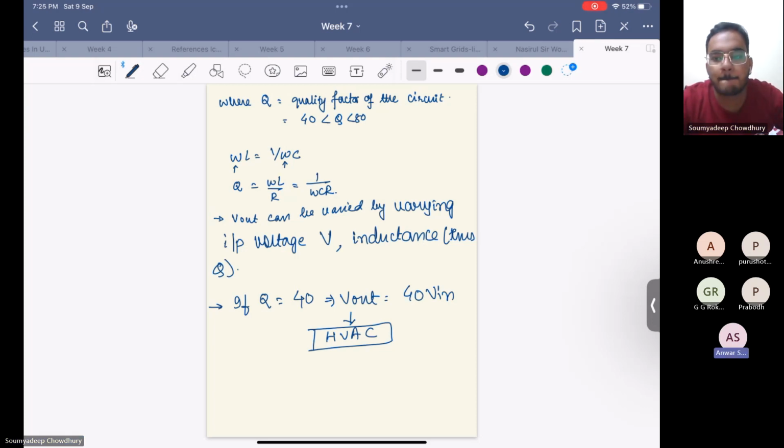Yes, sir. There are two types of testing that we usually do for cables. One is the measuring, which I think everybody knows and is very common. But if the cable is not in use for say 3 to 4 years continuously, or the cable has been cut in between for use in a different purpose, then we do this hypot test.